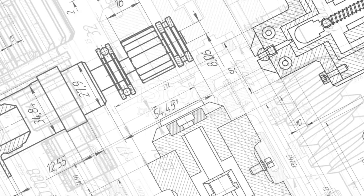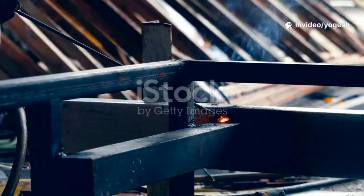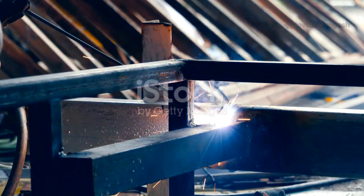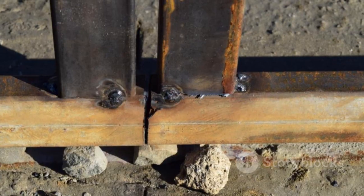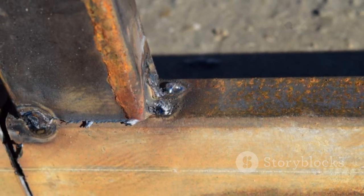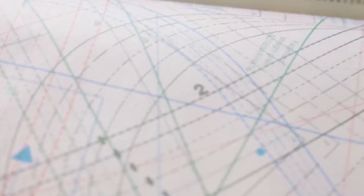Let's apply these concepts to a real design, a heavy-duty support bracket. The bracket's I-beam is welded to a thick base plate, requiring both strength and precision. A double bevel groove weld is specified at the web, with size noted to the left of the symbol. Fillet welds reinforce the connection, shown by adding the triangle symbol to the same reference line. The all-around circle indicates the fillet weld wraps the entire I-beam profile.